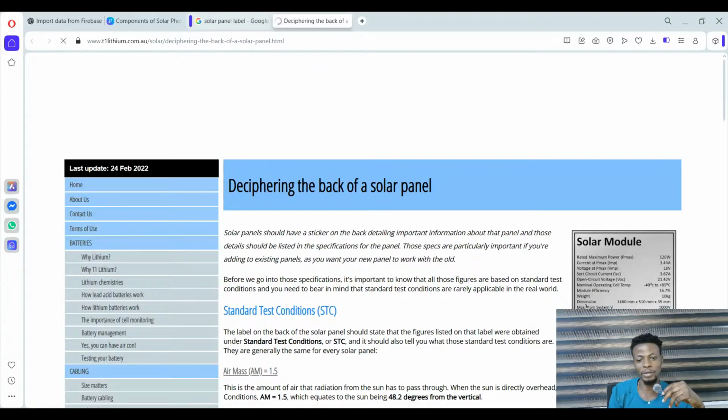You mistakenly connect live and neutral together, and before you realize it, the next thing is a spark, a very loud one for that matter. I've experienced it a lot of times. What happened is that you tried to cause a large current to flow. You short circuited that path of current, you short circuited the system. That is why you had that spark.